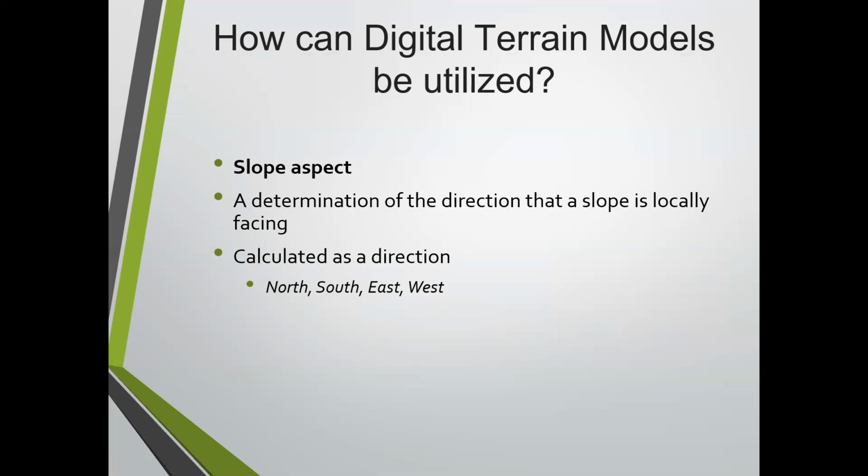And you can further color code it. So your arrow can be coded so that, let's say, green is going to be a slope between 1% and 5%, and red is going to be a slope between 5% and 10%. So you can not only get aspect, but you can also use it as a slope. That's why they call it slope aspect.